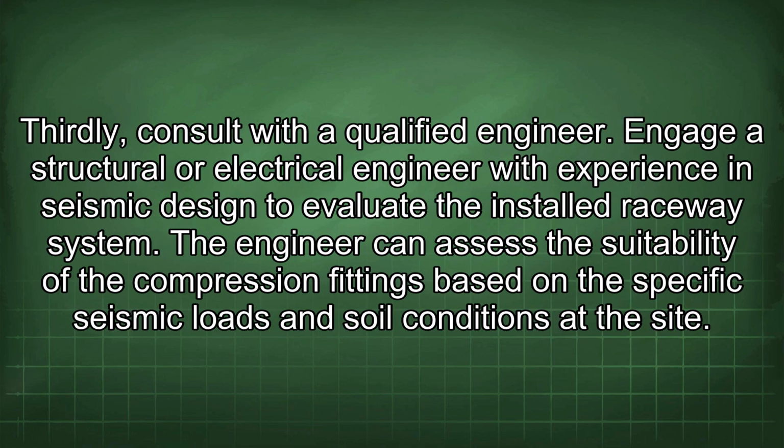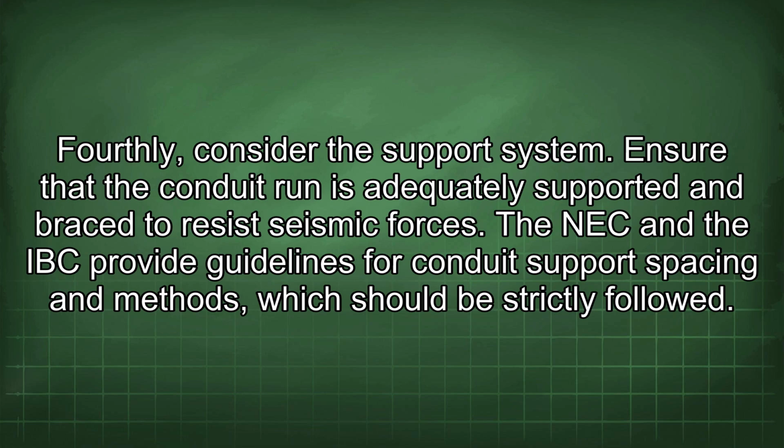Thirdly, consult with a qualified engineer. Engage a structural or electrical engineer with experience in seismic design to evaluate the installed raceway system. The engineer can assess the suitability of the compression fittings based on the specific seismic loads and soil conditions at the site. Fourthly, consider the support system.